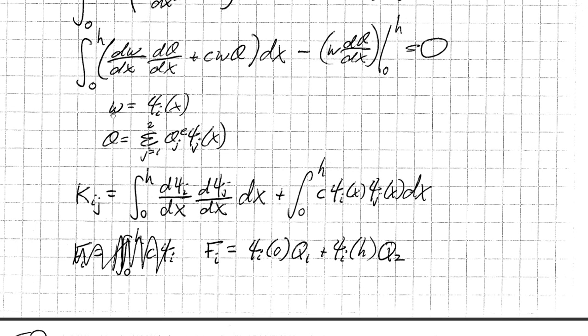Also, we're again going to stick with the Galerkin form where my weight function is my interpolation function. Here's my temperature that we approximate by constants at the nodes for an element E. Here's my interpolation function. So again, these have the same form. Alright, so as we discussed last time, we have a matrix Kij.